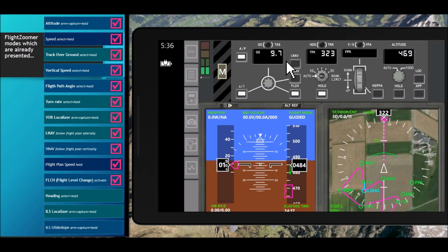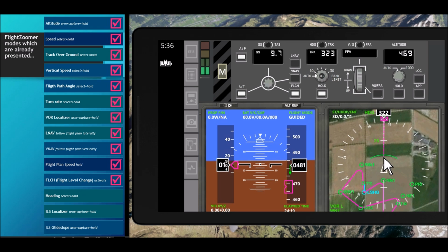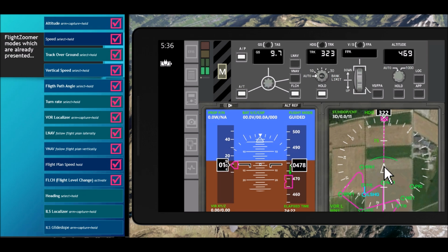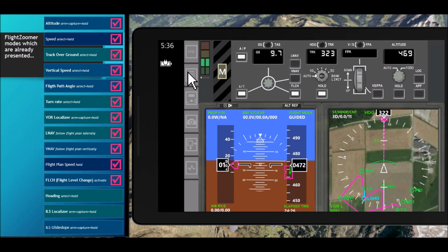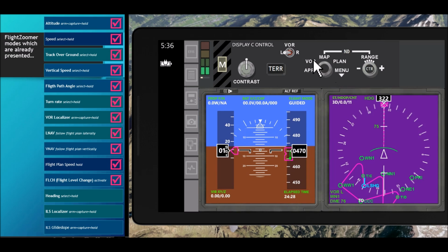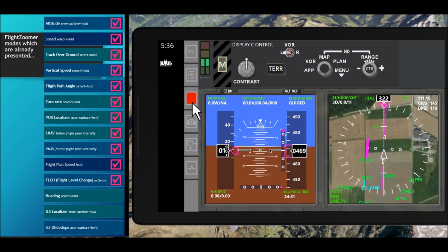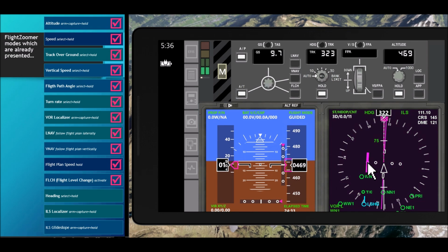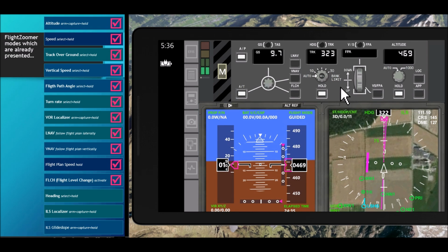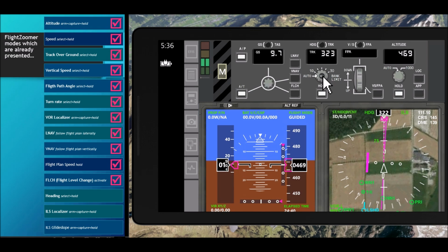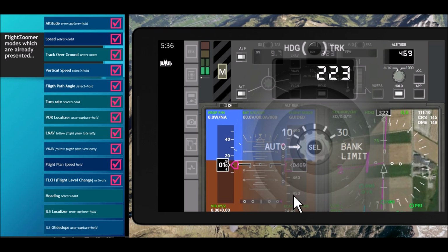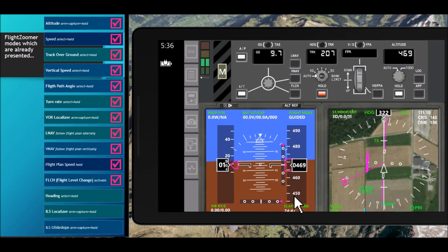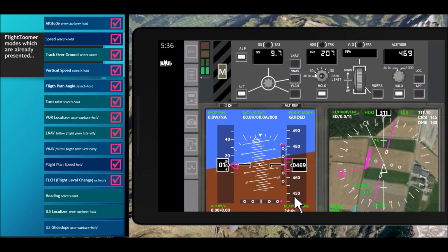With the flight level change mode. This is the green banana. At this location I will have reached the armed target altitude. So in the FIS, let's switch to the approach display mode. We see now the deviation indicator for the ILS. Speed is reduced, the altitude is correct. Let's set the direction which we will have to intersect the localizer. Track ILS 207 confirmed.